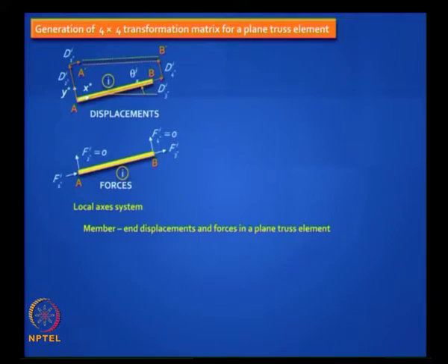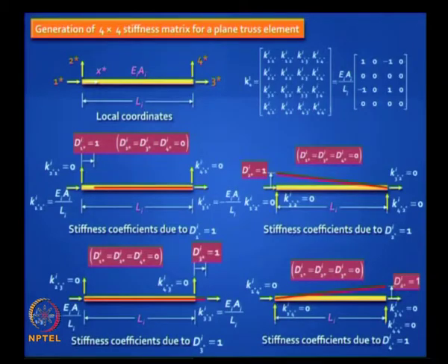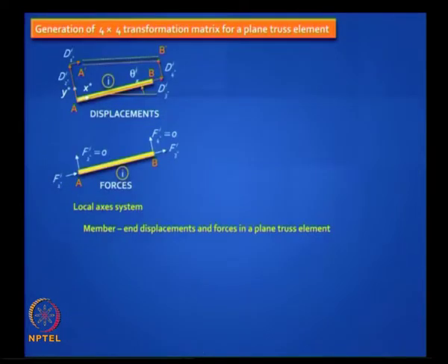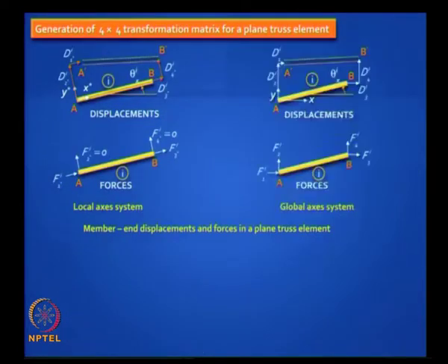You got a 4 by 4 stiffness matrix. In that stiffness matrix, remember there were 0 columns and 0 rows. The second and fourth rows and columns were 0 because they correspond to the shear forces. They are rigid body displacements. Okay, but in this, you remember this.